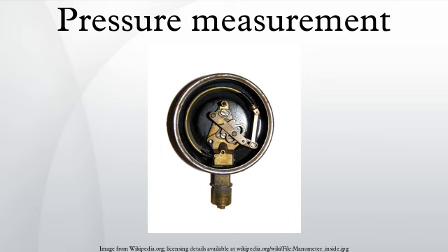There are two types of gauge reference pressure, vented gauge and sealed gauge. A vented gauge pressure transmitter, for example, allows the outside air pressure to be exposed to the negative side of the pressure sensing diaphragm, via a vented cable or a hole on the side of the device, so that it always measures the pressure referred to ambient barometric pressure. Thus a vented gauge reference pressure sensor should always read zero pressure when the process pressure connection is held open to the air.